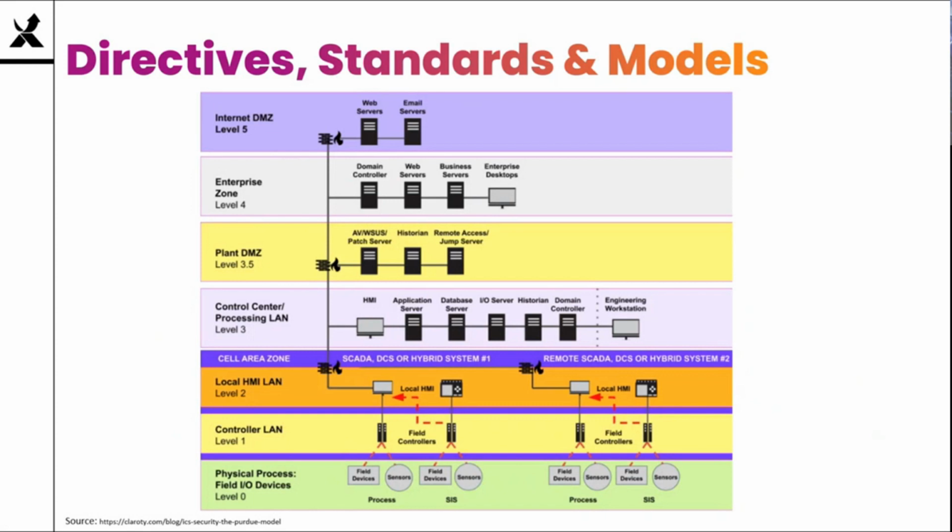Level 3.5 is typically created with the help of firewalls, and in an industrial DMZ, IDMZ, it creates a barrier between the IT and the OT networks. Solutions like jump boxes can provide limited access to the ICS systems from IT environments, but this buffer can also help to prevent infections within IT environments from spreading to OT systems and vice versa.